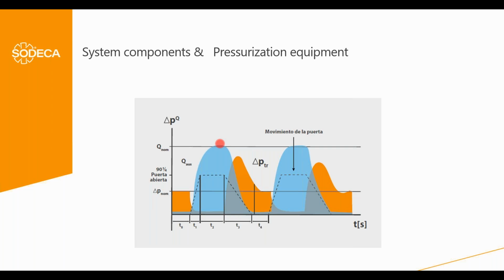It's necessary to do a fast regulation, a fast acceleration through the PID of the inverter, but let's say that it's more or less easy to manage. Of course, this will depend on the relation between the maximum airflow and the minimum airflow. The bigger the acceleration, the more difficult it is.